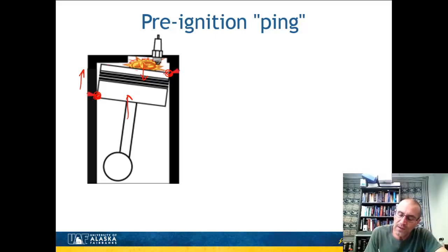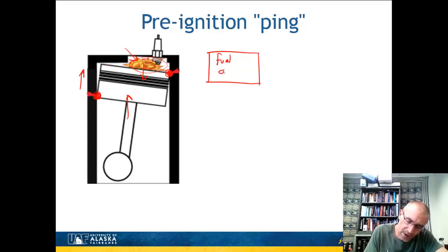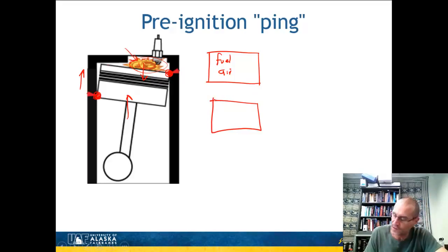The thing that becomes important is you want to know what is the temperature that's occurring inside here, because this actually can cause warping of your piston head. So let's look at solving this problem. Effectively, because this explosion happens fairly quickly, I have a constant volume system. Think of a rigid tank that has fuel and air in it, and then it spontaneously combusts, and it becomes a rigid cylinder of the same size, but it all has exhaust gases. So that system goes from there.